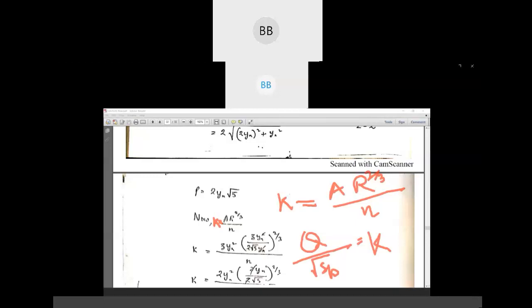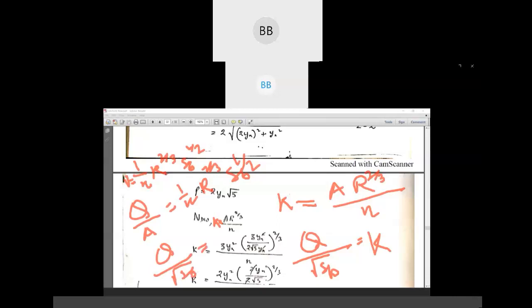So this is your Manning's equation: V equal to 1 by n R to the power 2 by 3 Sb to the power half. In place of velocity we can write discharge by area, equal to 1 by n R to the power 2 by 3 Sb to the power half. So Sb you bring to this side, Q over root Sb, and area you bring to the right hand side.